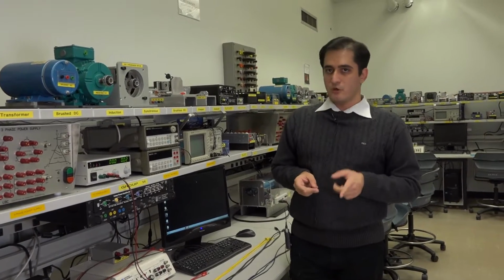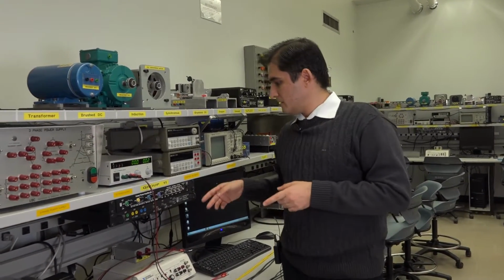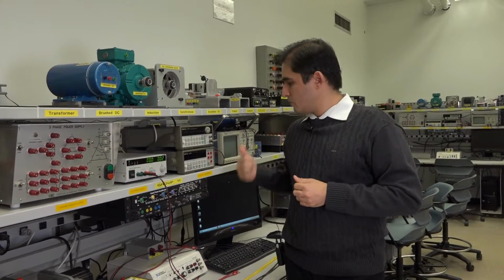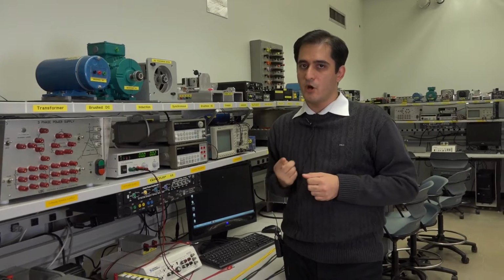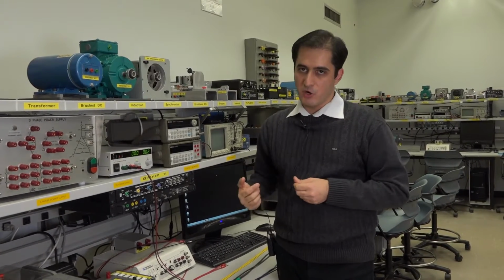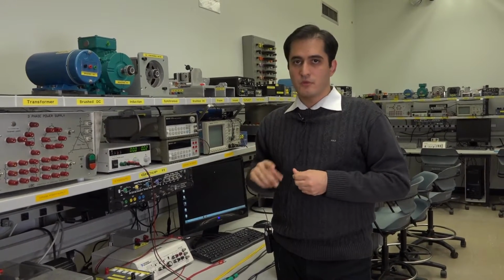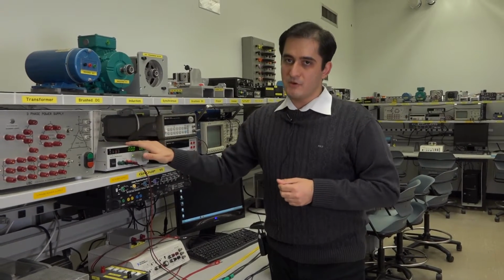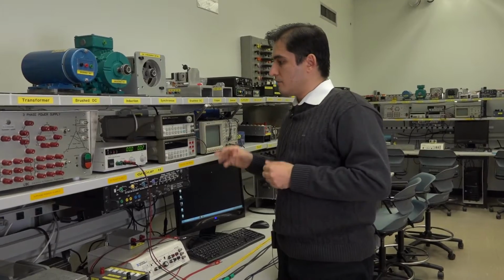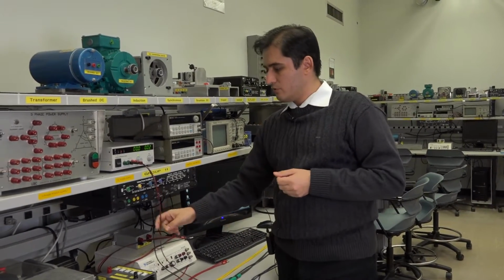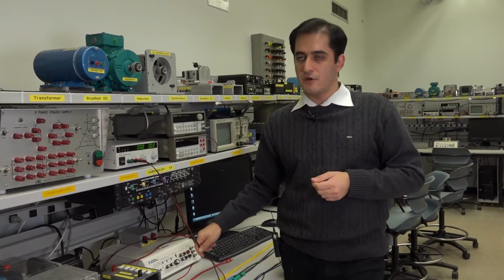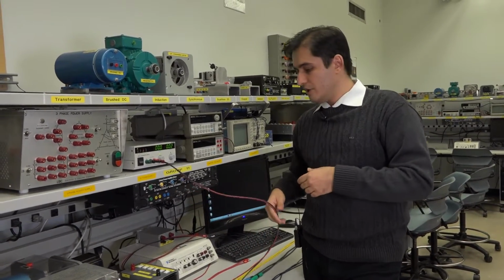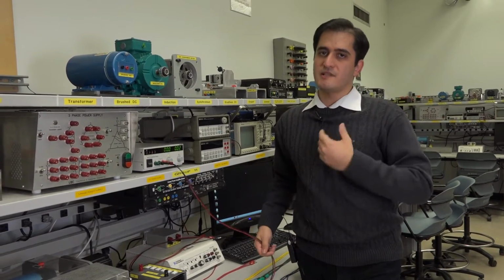It is important to note that with the measurement that we did with the multimeter, we repeated the measurement in one case with 1 wire as a probe and then 2 wires as a probe. You should remember that you have to repeat the same procedure with the DC power supply, meaning that in one case you need to apply the voltage and measure the current using 1 long wire here, and then you need to double the length and do the same again.